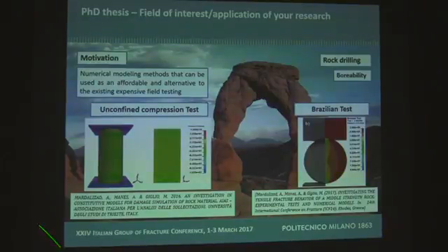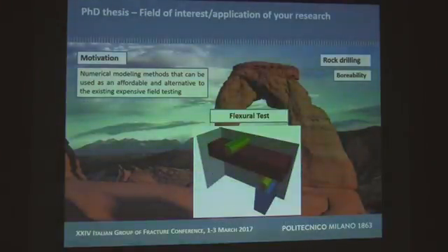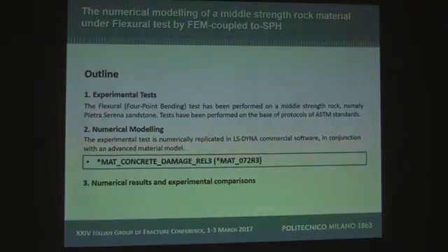In these studies and in today's presentation, I will present something about the Flexural test, which can be used in order to validate the numerical result that was previously calibrated and prepared. So, as the outline, I will show something about the experimental tests that were conducted in the Class C laboratory of Politecnico di Milano based on the protocol of ASTM standard, and the numerical models which are replicated in LS-DYNA commercial software in conjunction with an advanced material model which is called KCC or MAT72R3. Finally, the numerical results will be compared to the experimental ones.